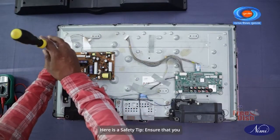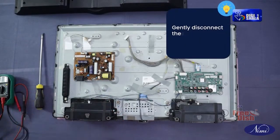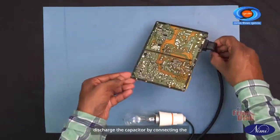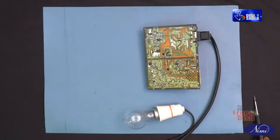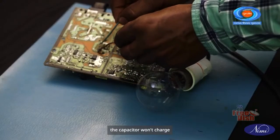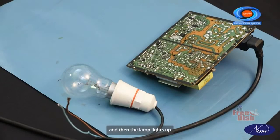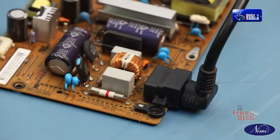Here is a safety tip. Ensure that you gently disconnect these to avoid any damage. Handle the board cautiously due to the fully charged capacitor. Use a discharging tool to safely discharge the capacitor by connecting the cables from the discharging lamp carefully. As the fuse is working in this case, the capacitor won't charge and the lamp stays in an off position. But if the fuse is not blown, the capacitor charges up and then the lamp lights up as the capacitor discharges.